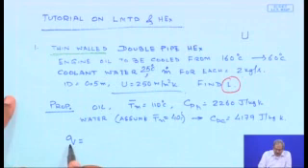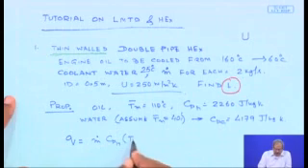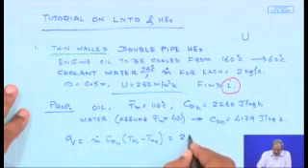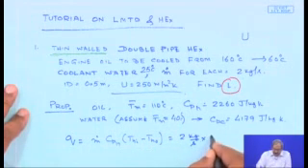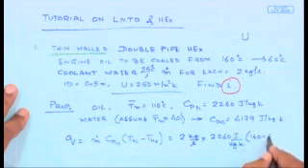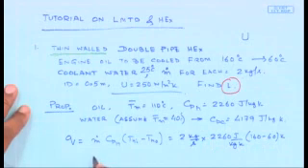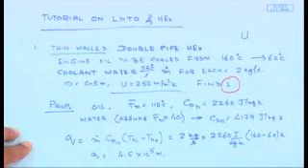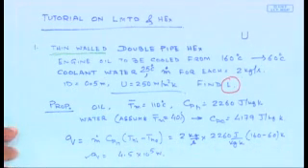First of all, I can find out what is the total heat transfer which is taking place. That is nothing but m Cph times Thi minus Tho, simple heat balance. So this would be m, given as 2 kg per second, times Cp, which is 2260 joule per kg per Kelvin, and the temperature difference is going to be 160 minus 60 Kelvin. So this value of Q would be equal to 4.5 into 10 to the power 5 watts. A simple sensible heat change, there is no phase change involved. So this would give me the value of Q.